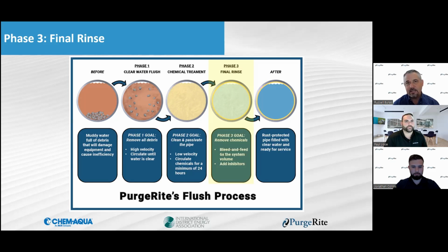And this is one thing that a lot of people miss. If you had a 100,000 gallon system, it's going to take you at least, in most cases, 500,000 to 600,000 gallons to rinse it. We deal with systems that take millions of gallons, and you start thinking about the size of it and the volume of how much water we're going through. It's unreal. But a lot of times we've seen sometimes even 8 times the volume. So just keep that in mind.